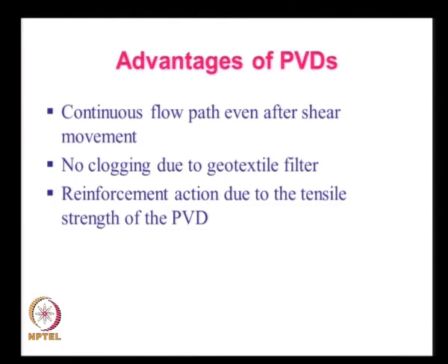in the ground, and because we have a geotextile filter, there will not be clogging. That means that we have to properly select the geotextile cover based on the in situ soil properties, based on the grain size distribution and other things. That is, all the principles that we have for the design of filters are applicable in this case.